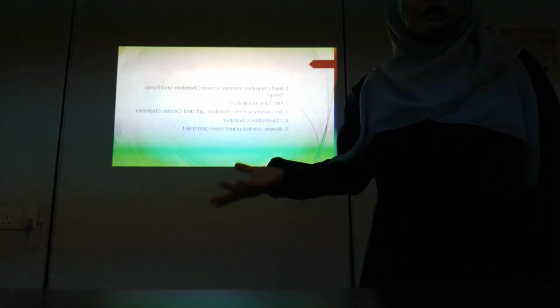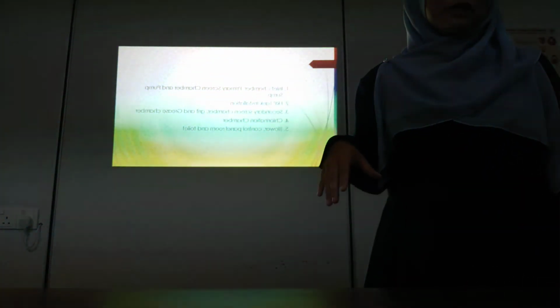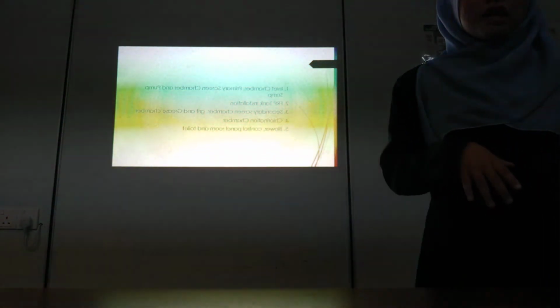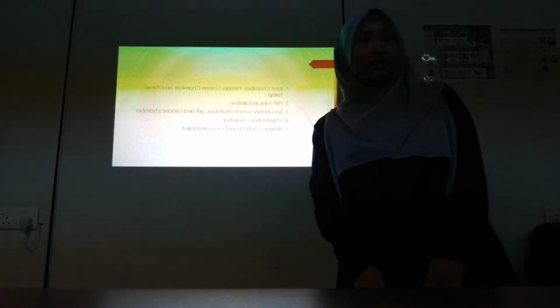The steps are, after the mobilization, to construct the inlet chamber, primary screen chamber, pump sump, FRP tank installation, chlorination chamber, and also the blower, control room, and toilet.